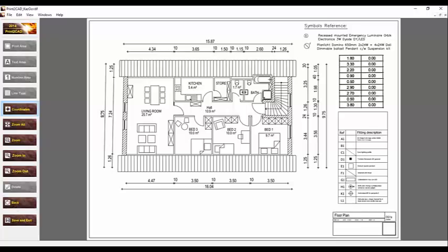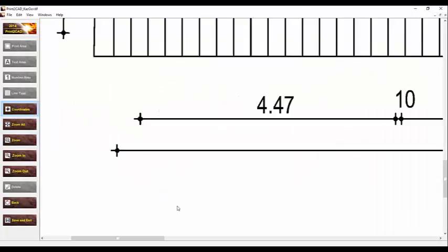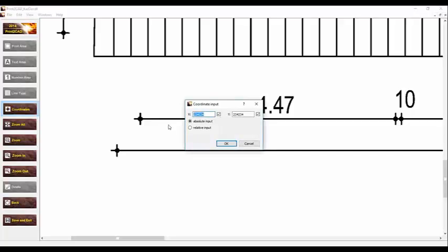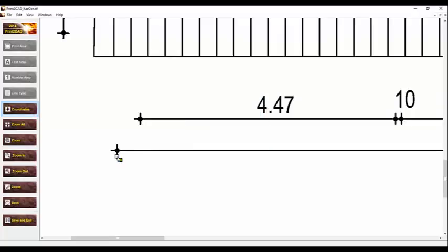And let me use this. This is not complicated. So, for example, I snap here the end of this line, and I decide this will be my coordinate 0. But I'm not interested in the y coordinate. Calibrate this one point, and everything you snap in this area is coordinate 0.